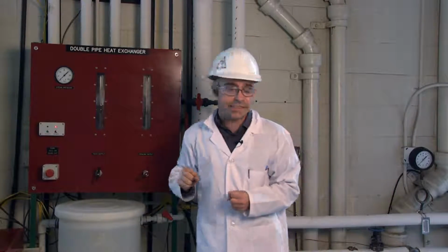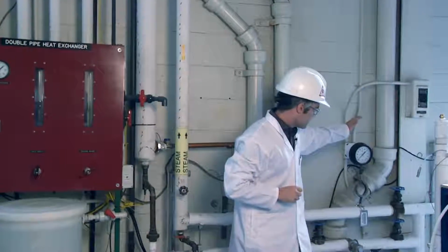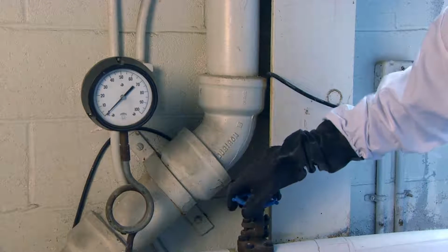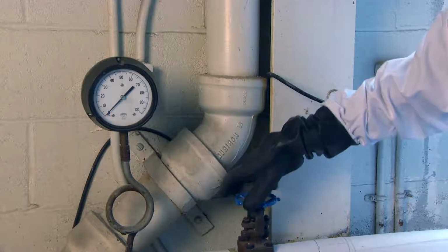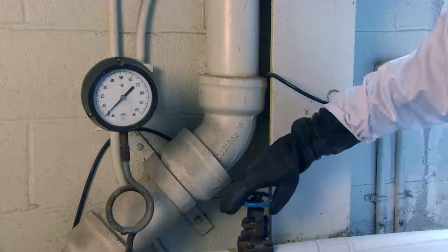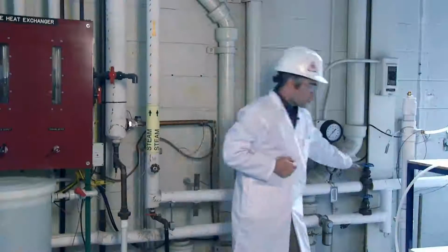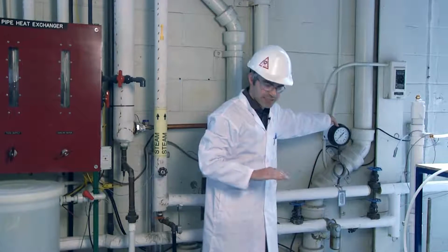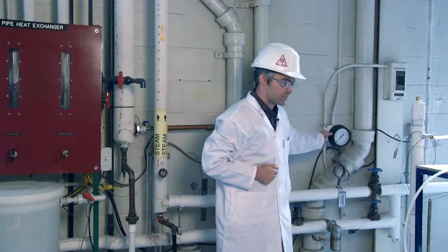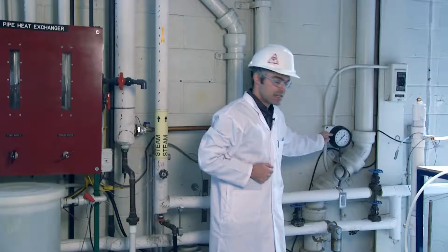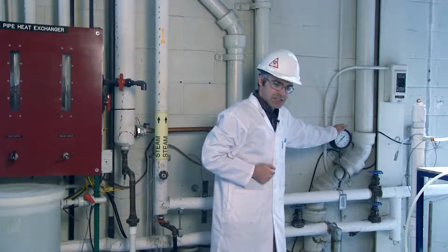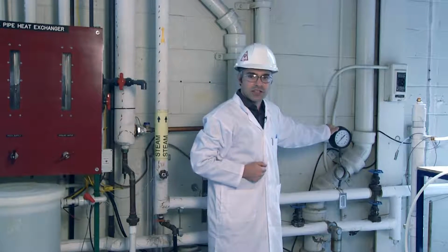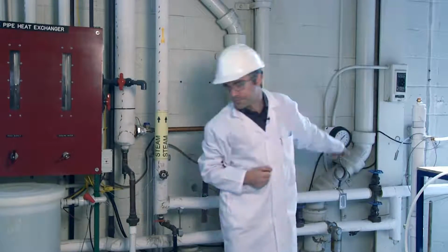In order to engage the heating steam, you'll come over here and you'll turn on the master steam valve. Only do this with the TA supervision. Once the steam has been engaged, you'll notice the pressure of the steam. Currently in the summer, we have no steam, but you should see approximately 20 to 30 pounds per square inch gauge. If you do not see this number or see much higher, seek out one of the instructors immediately and we'll correct the steam issue.